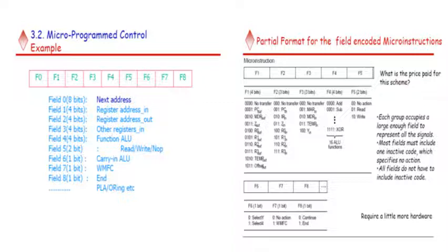However, the microroutine in the figure shown here does not terminate by producing the end signal. In this organization, the starting address is not specified by a resetting mechanism triggered by the end signal. Instead, it is specified explicitly in the F0 field.